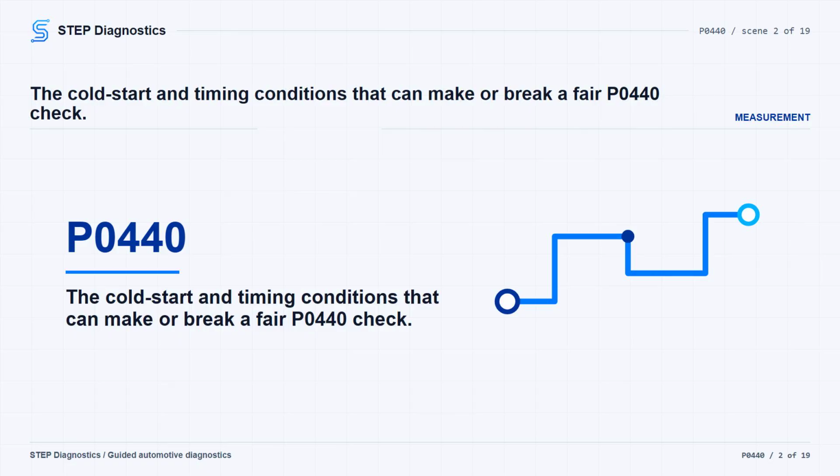Some EVAP monitor logic uses an engine on/drive cycle for a minimum of 2-5 minutes, and the engine on timer is clipped to a maximum of 26 minutes on any given trip. There is also a 12-minute delay time where the PCM ignores ESIM switch input. If the event goes a maximum time of 17.5 hours without an ESIM switch closure, the monitor logic keeps tracking that failure. The accumulation fail timers are calibrated at engine on 100 minutes and engine off 70 hours.